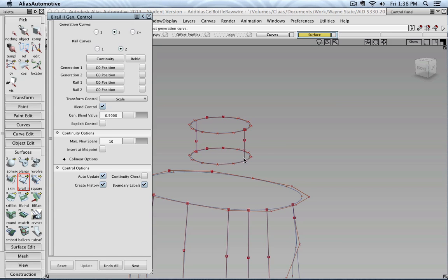However, along those two vertical generation lines, I would like that the surface that starts here grows over and stops here. The way it stops, it should be shaped so that it looks like it is flowing smoothly into the mirrored surface on the other side, basically the one the symmetry function is going to create for us. So to do this, we can turn on implied tangent.